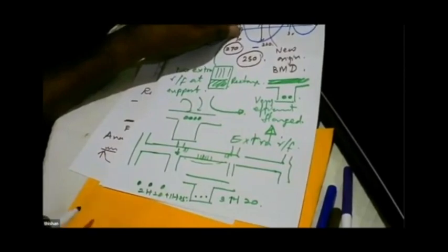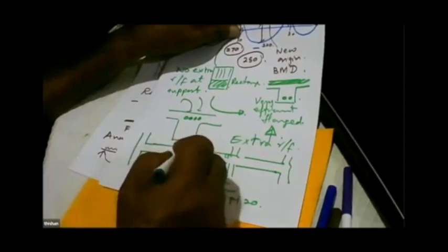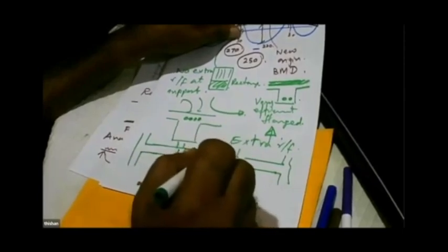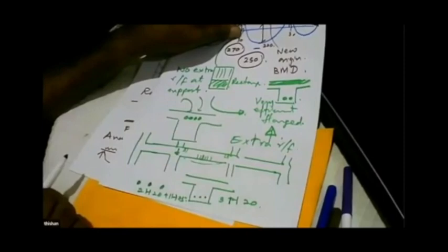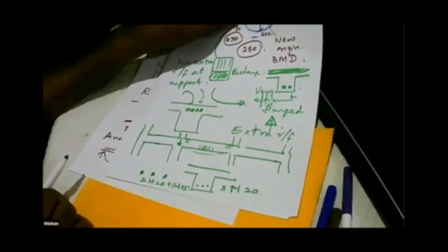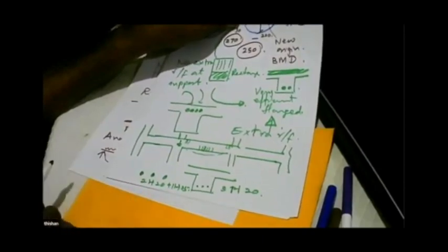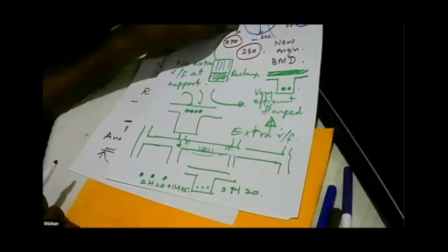Because even if the beam is overloaded, which section will have a problem? Yes. At the support, it will form a crack. No problem. That is accepted. What will finally fail? The span. What are you going to do? You have to put a little extra reinforcement in the span where it's going to fail. Will it ever fail, even if it is overloaded?